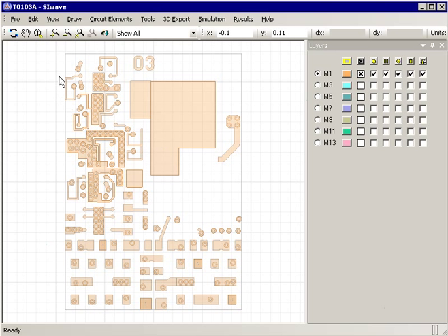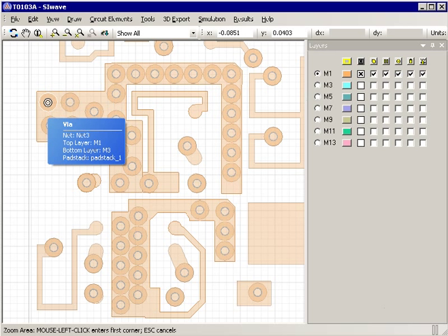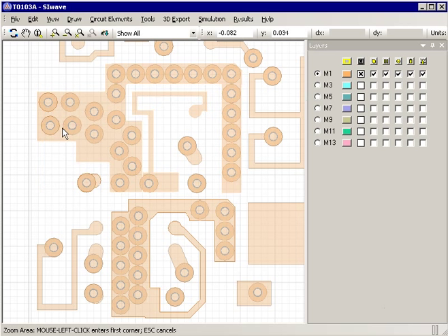Now what you can see here is that we actually have different kinds of entities. Wherever we found a flash and a drill coincident, we actually built a pad stack. So you can see we have the via that goes from M1 to M3 there. All right. And then we also have the plane on M1.